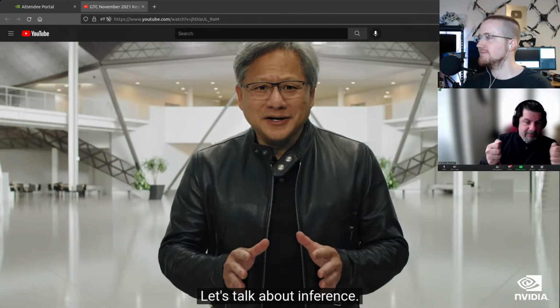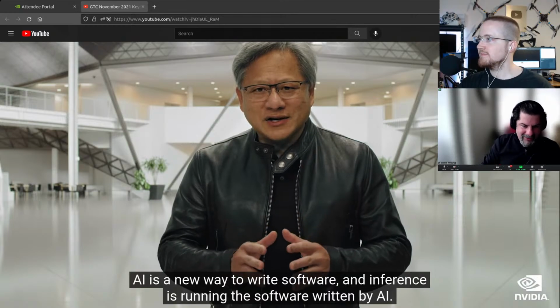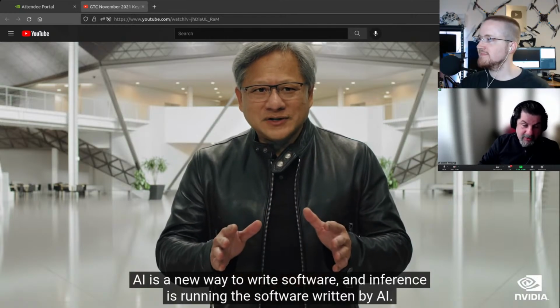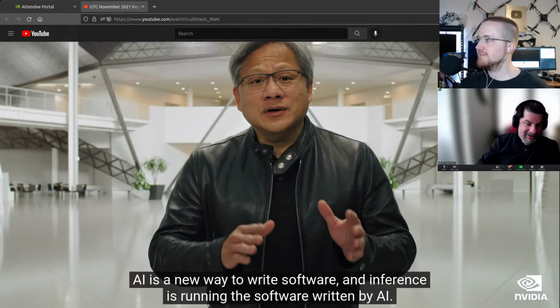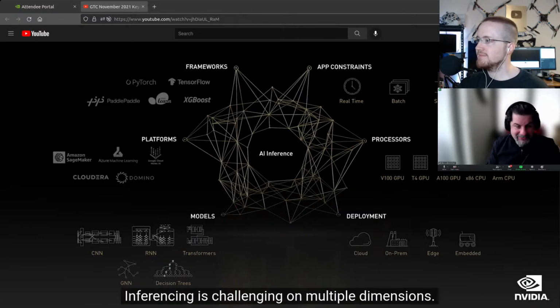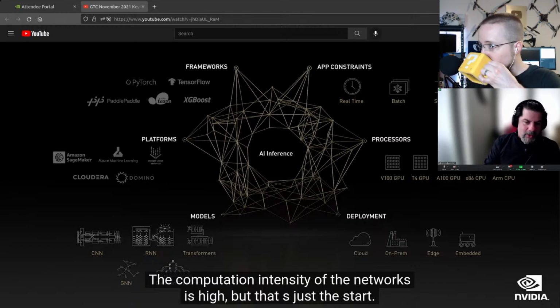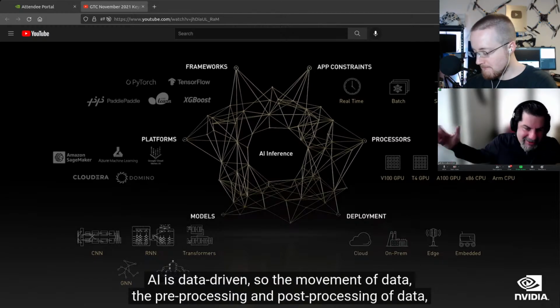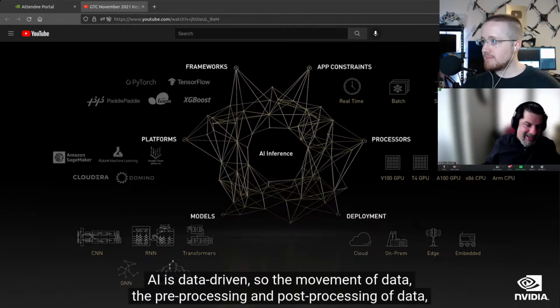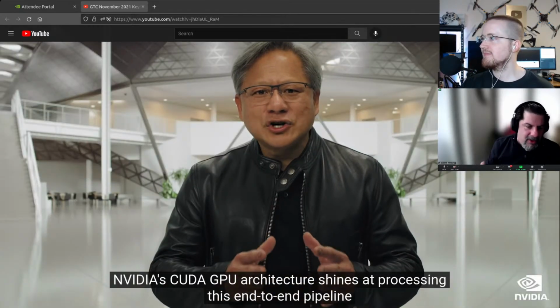So we take the computer that would actually be in the car that has connectors for the sensor inputs, and we replace those sensor inputs with outputs from the simulator, like video out from the simulator, plugging right into it. So it has to run in real time, but worlds that are continent scale, and each pixel has to be faithful to what the actual camera would see.